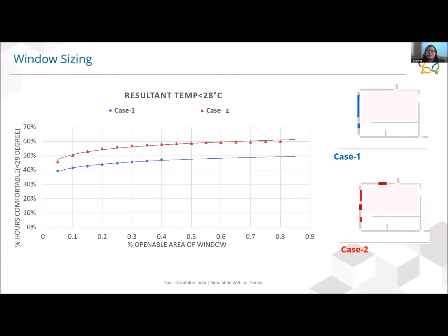There are a lot of various factors which come into play when you are designing for windows. That could be your air pressure, the direction of the window, location of the window, wind speed which is going to come in, if it is cross ventilated, or if there is ventilation on only a single side. All of those factors weigh in, including the percentage of opening, when we are designing for a naturally ventilated space.